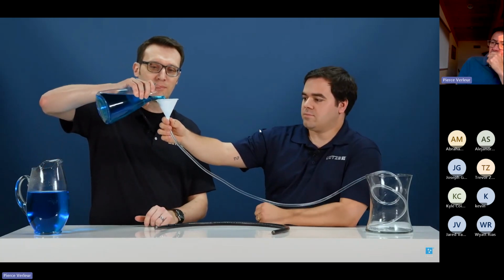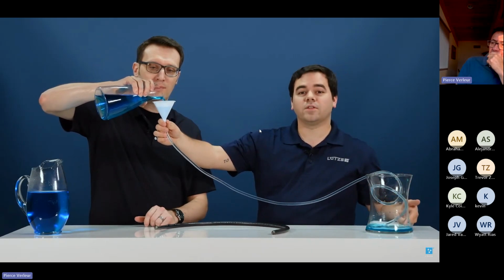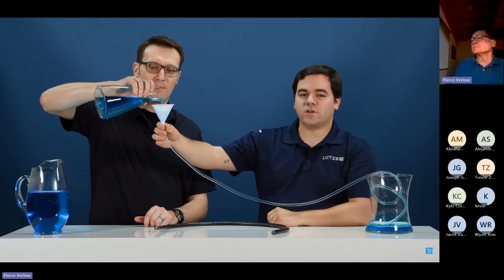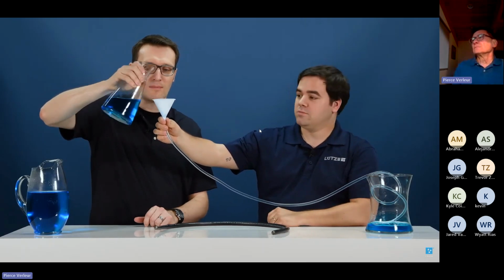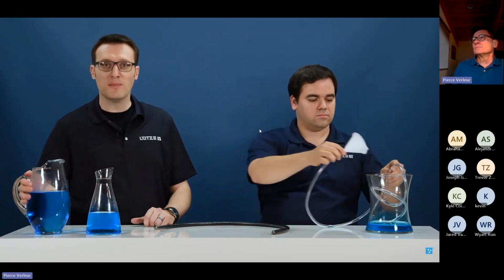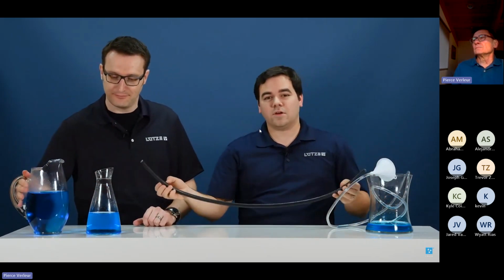So as you turn the drive on, that energy, or this blue liquid, has to fill up the hose before it's available at the motor end to turn the load. And this requires quite a bit of energy output from the drive, depending on your cable. Usually, you would solve that problem by going to a bigger drive. One thing that people often don't consider is that you can also solve that problem and stay at a smaller drive size by going with a low capacitance cable.